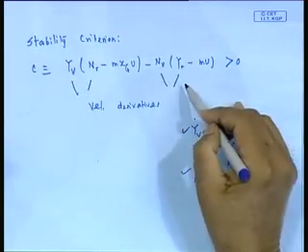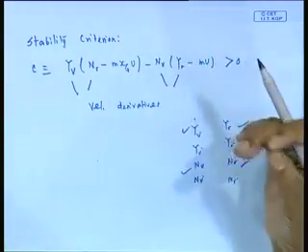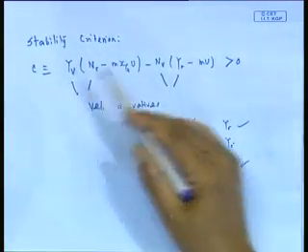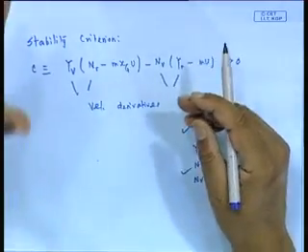All these are hull forces created because of the flow past the hull. Look at YV: because the ship is going at an angle of attack, a Y force is created. NV, because of the same thing. So you will understand this part.